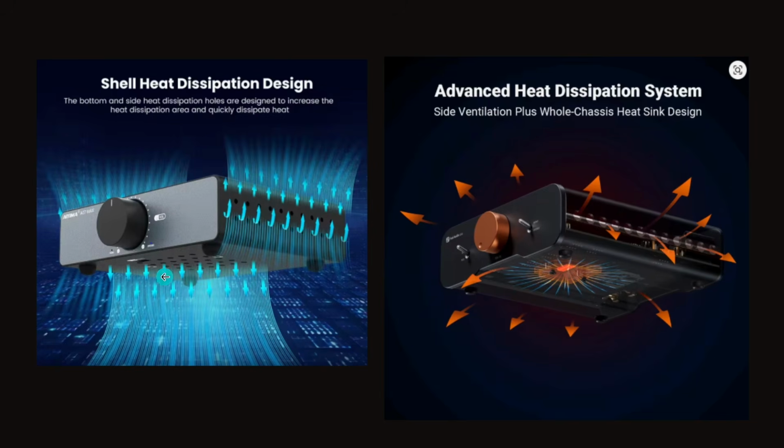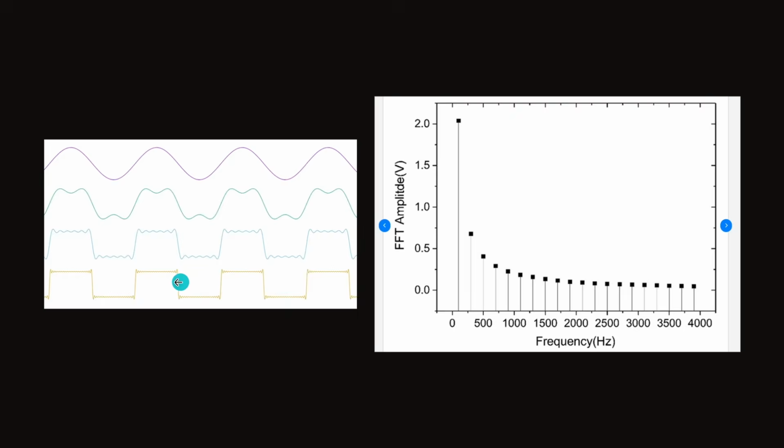Yeah, when you turn it into a vertical position, then yes, between those holes there will be a nice chimney, and we will start to cool our system. If your amplifier is overheating, just make a stand and put it vertically, and then everything will be fine. Here the holes are even better. If you take this amplifier and put it vertically, you can get maximum power out, and this amplifier will have a nice life.